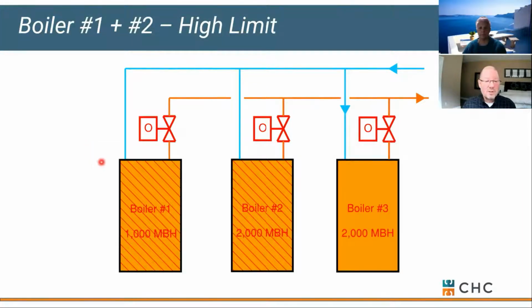Add manual balance valves to each boiler. I'm with you on manual balance valves, kind of like auto flows. The challenge is if I put it on the discharge of each boiler, system pumps are on drives. Manual balance valves work really well for constant speed, but as soon as a pump changes its pressure, like it would on a drive, you change the flow rate across the manual valve. That can create a problem. Auto flows would be a better choice than a manual valve. And again, I'm not picking on anybody, just running through the options here.